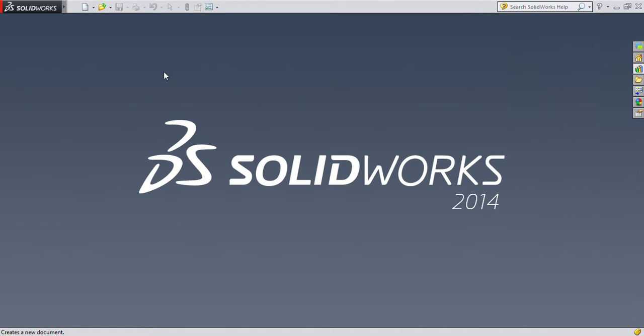So let's begin. First thing you have to do is to press here, you can see, or you can go to file and click on new. As you can see, you can also open it by pressing Ctrl plus N. Okay, then a bar will show up. It will contain three parts. Number one is part, number two will be assembly, and number three will be drawing. So we will be working today with part, that is the first one, and click OK.